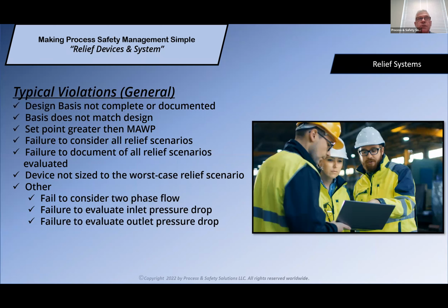Remember, I said when we first started this discussion that you must document all and evaluate all relief scenarios that are potentially there. 24 of them for a matter. Most of them you can go through fairly quickly and say they don't apply. But typically 2 to 3 of them apply in almost every situation. Fire case, blocked in case, loss of cooling case, et cetera. There are numbers that apply in just about all situations that you must look at and evaluate. So you may have 3 scenarios that apply. You must document what are the relieving scenarios for each of those.